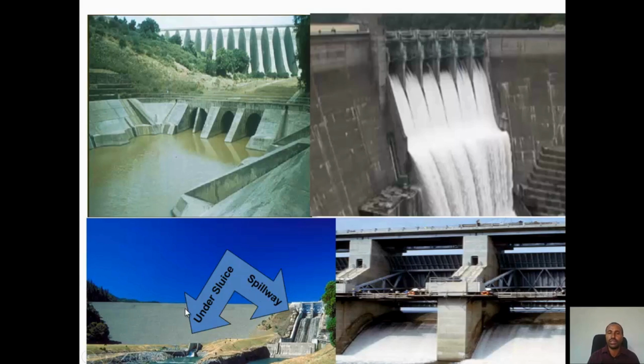And you can see this picture again. This is an embankment dam. So you have a separate spillway, which is a chute spillway, and an undersluice. You can open the undersluice portion just to dispose of excess flood when it comes. This is a radial gate spillway. You can see again, these are all dam appurtenant structures or dam outlet works, which means just conveying or discharging excess flood or some extra flood when it comes.